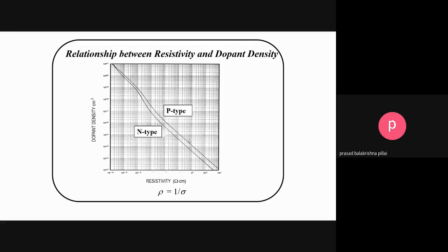See, actually, if a full wafer is available, then one can know from the primary and secondary flats, and the position of the primary flat. If you go back to the earlier discussion, we discussed it in the first, second, or third lecture. There you will see that for different orientations, there is a primary flat and a secondary flat. The placement of the primary flat tells you the type. I don't have the picture here today. So that is one way, if a full wafer is there.